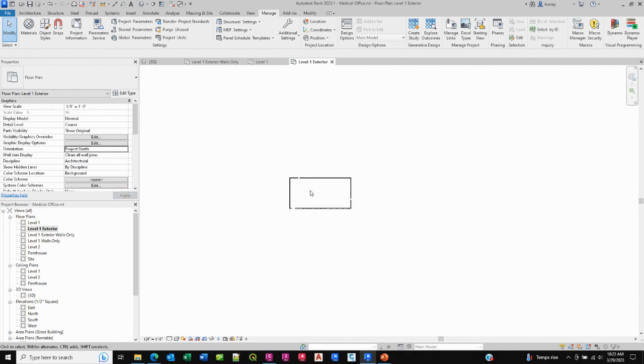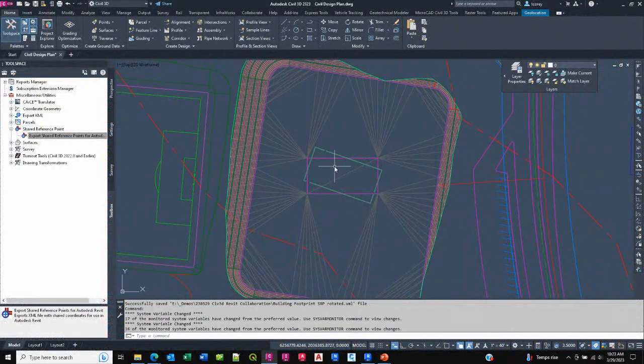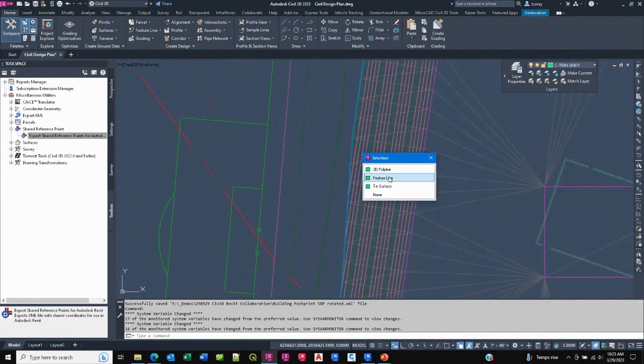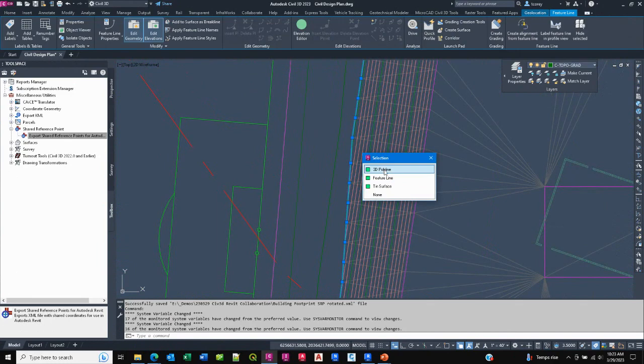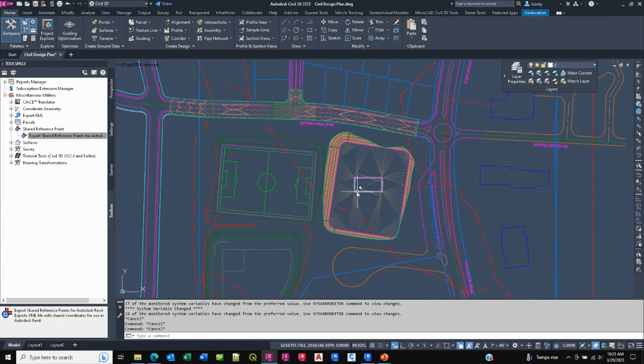Okay. So we've placed that. That's all good. So now I can take and publish my surface model. Okay. So I've got a surface that kind of covers this building pad, comes down here and daylights. That's all I want to send. Actually, that surface covers a bigger area, but I added a boundary with a 3D polyline to clip that off. So I'm not sending as huge of a surface. So what I'm going to do from here in Civil 3D is I'm going to publish my surface.